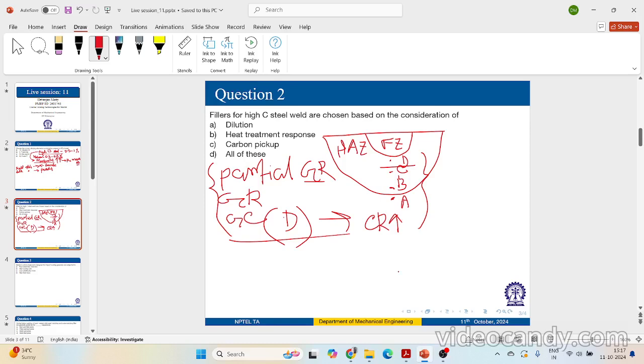And even the grain size also will be large over here. The grain size is also large for position D. And because of those things, it will promote martensitic formation, right? So martensite formation tendency will be much higher for position D. Agree? Now, on the other hand, if you have lower cooling rate and smaller grain size, what will that encourage, what kind of microstructure will it form? It will form pearlite and ferrite kind of microstructure, right?